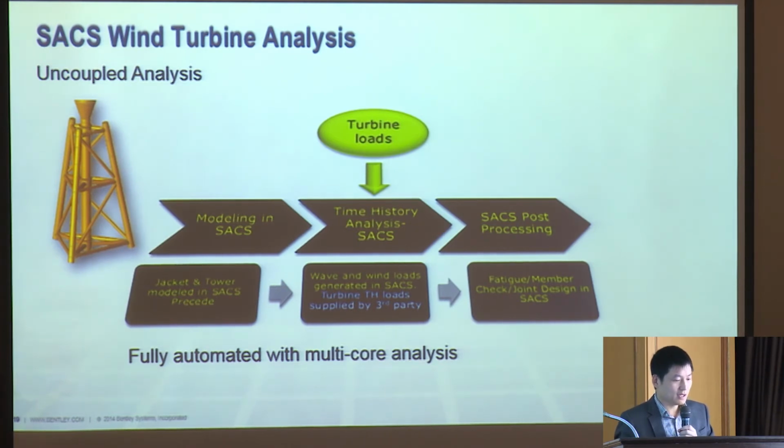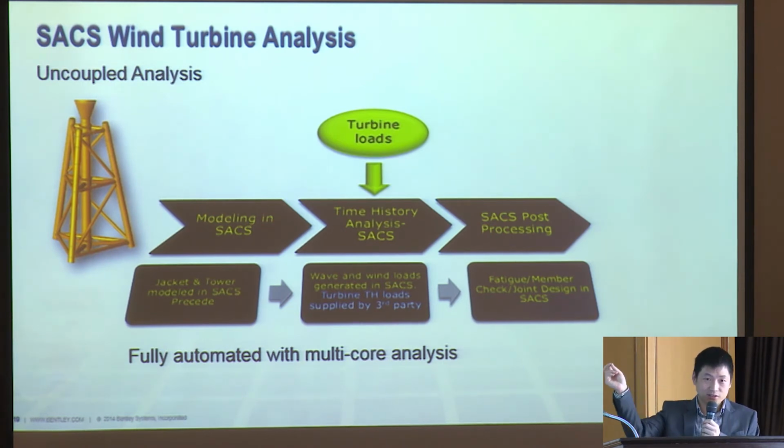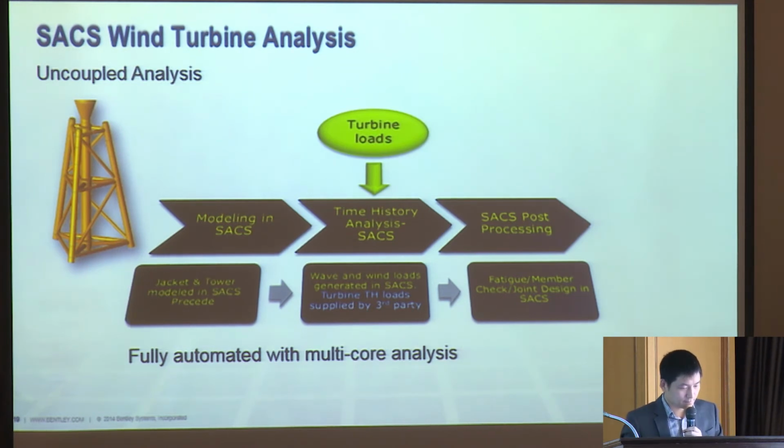And SACS will perform a time history response analysis to solve all the load cases in time history. Then, after solving all the load cases at each time step in the time history simulation, we can do the post fatigue and strength check in SACS.